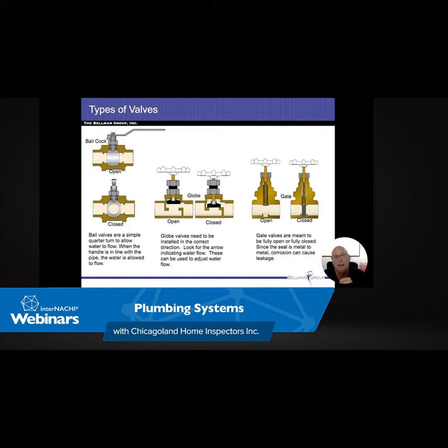So what they're going to do is measure the water level when it's at rest. Then they're going to, I forgot exactly how much it is, I want to say it's like 5 gallons of water. And they want to see how long it takes to fill up a 5-gallon bucket. They're also going to measure how far down the water level dropped during that time frame. And then they're going to measure the time frame it takes for that water level to come back up. Again, that's a drawdown test.